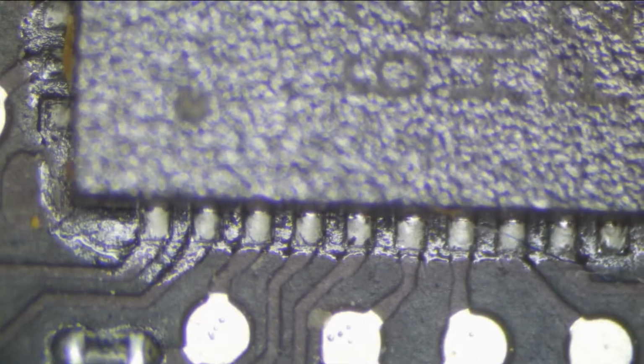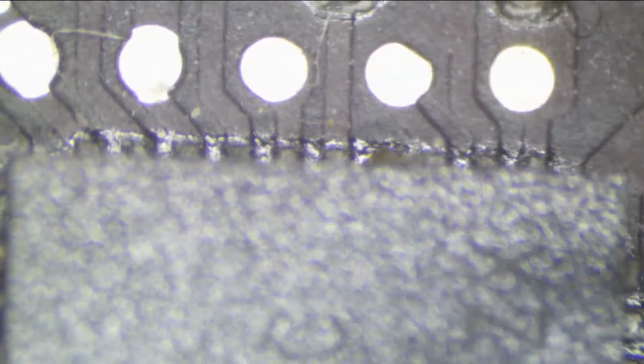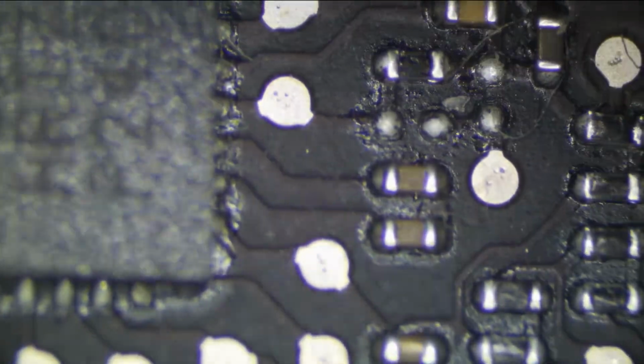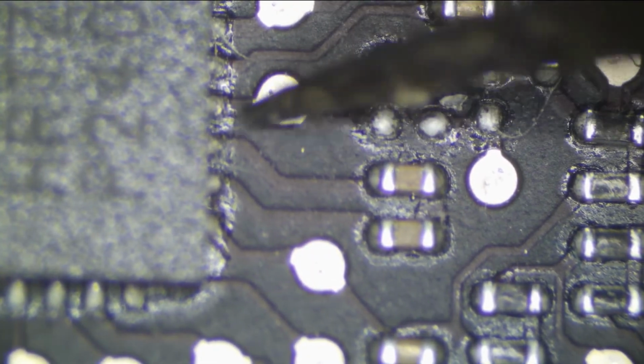This is how it's supposed to look. See how that looks normal? And you can see there's a definite difference on the other side. A little bit of junk or coffee there, but that's not too bad. That may cause our issue too, but I doubt it. What our issue is going to be is these breaks in the solder joints right here. So it's very apparent this is what's causing our issue.